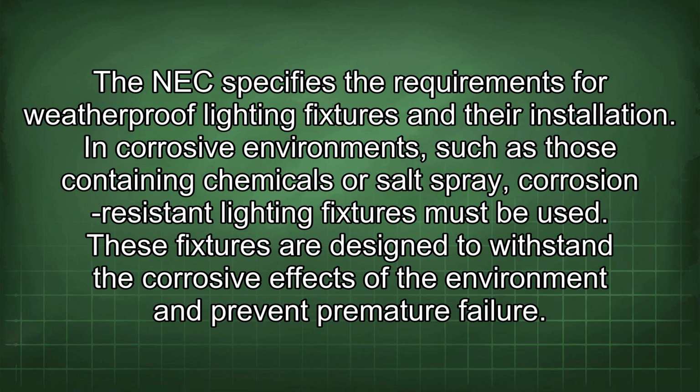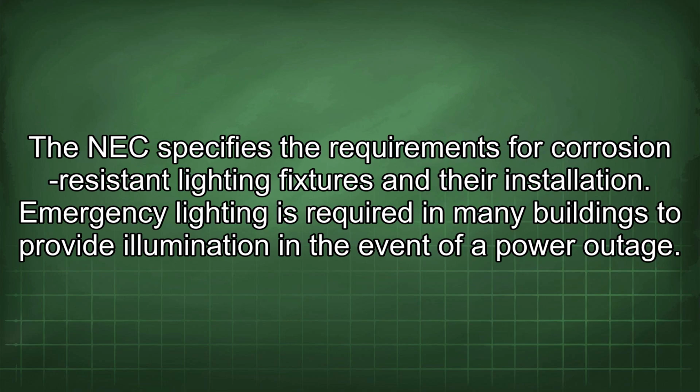In corrosive environments, such as those containing chemicals or salt spray, corrosion-resistant lighting fixtures must be used. These fixtures are designed to withstand the corrosive effects of the environment and prevent premature failure. The NEC specifies the requirements for corrosion-resistant lighting fixtures and their installation.